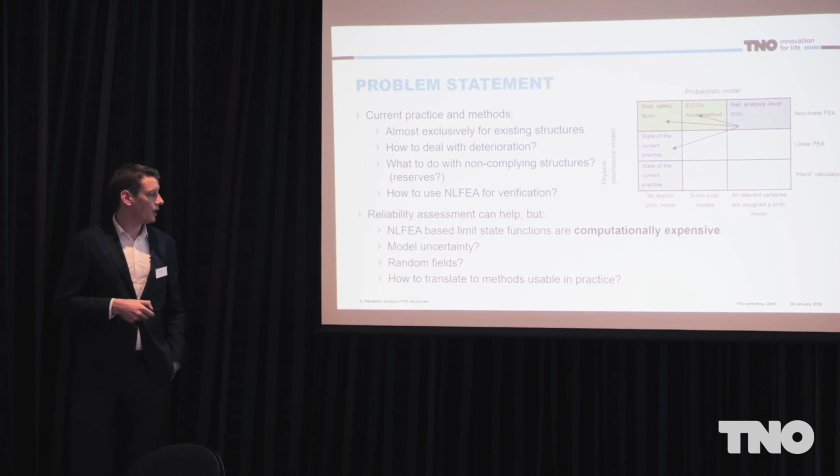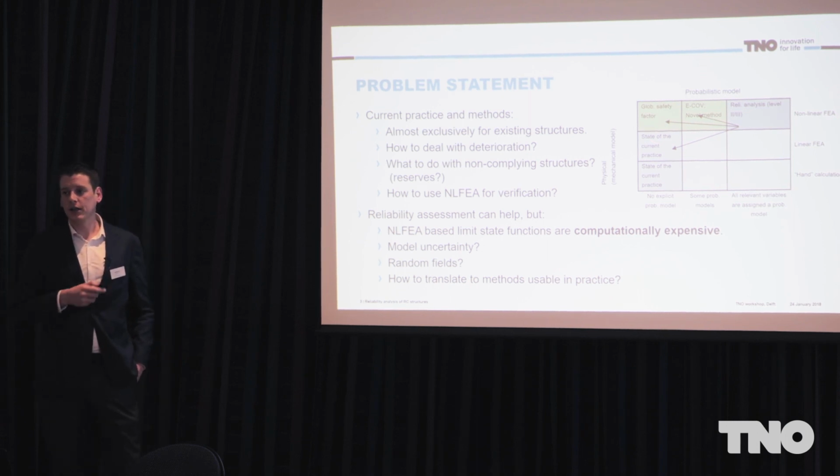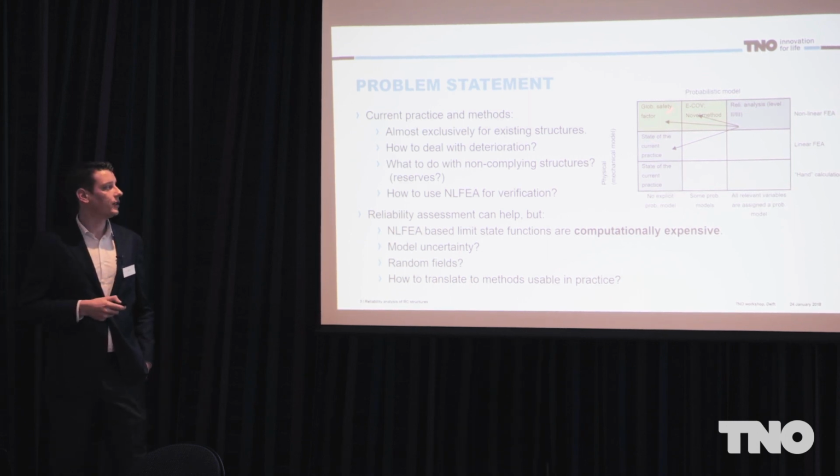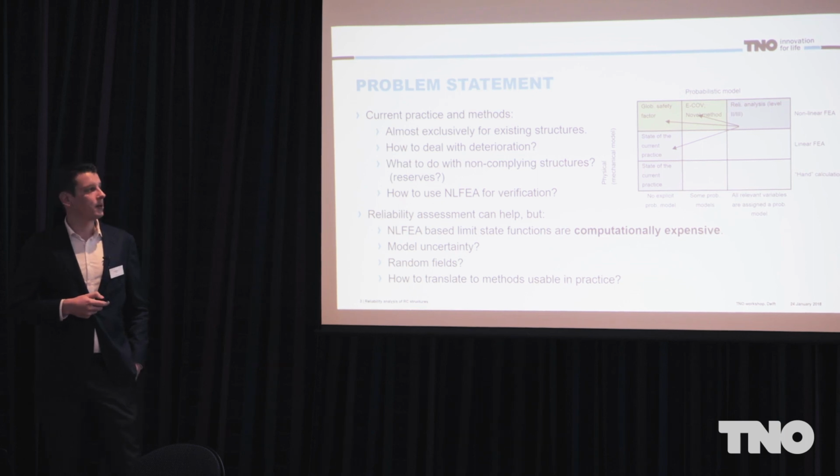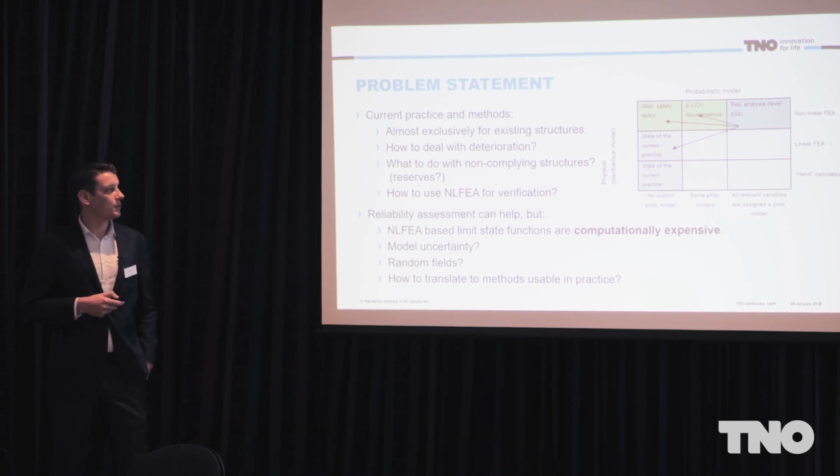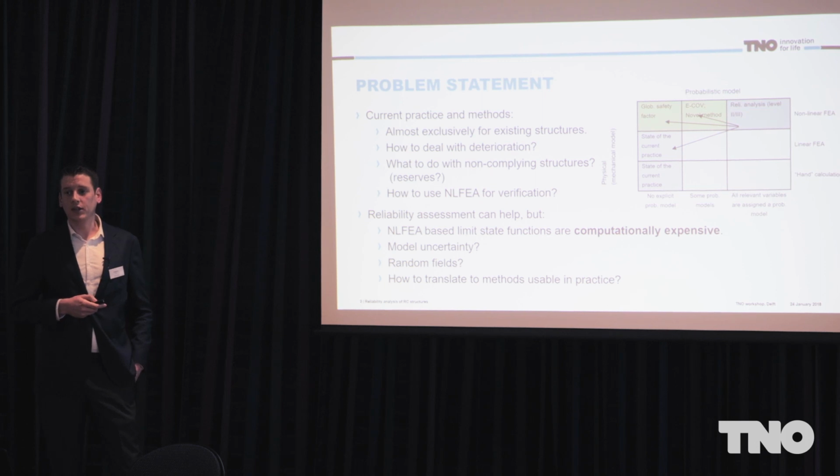And then the last question, which I just mentioned here in this table, is how to translate these structural reliability methods and the results into something which can be utilized by practice, because it's really not expected that practicing engineers will carry out direct reliability analysis.